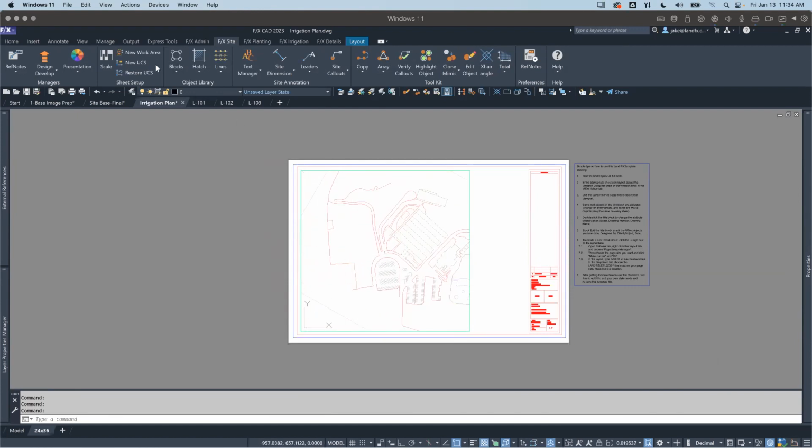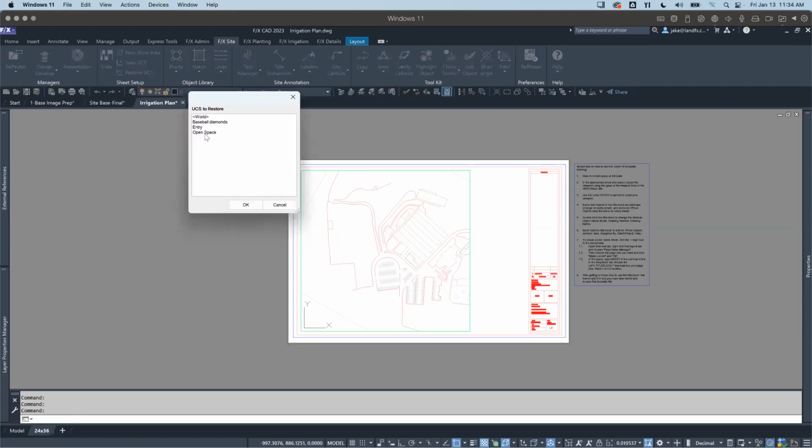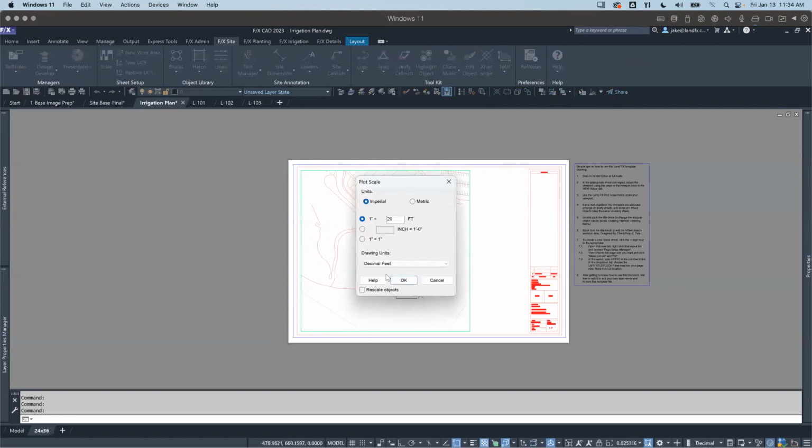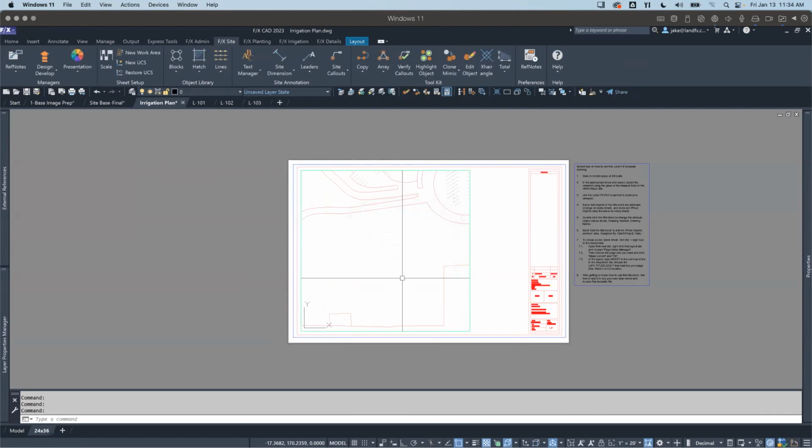Let's just look at this area really quick. As a case in point, we'll do the open space. We'll pivot it around and set its scale to 1 to 20 and see. You can see that it's also just not advantageous for us to do. So I could fit this into two sheets and I could fit the other side into two sheets. Really not the end of the day, but what that's going to give us is better legibility for the symbols. Things are going to fit a lot better than trying to jam them into a larger scale.